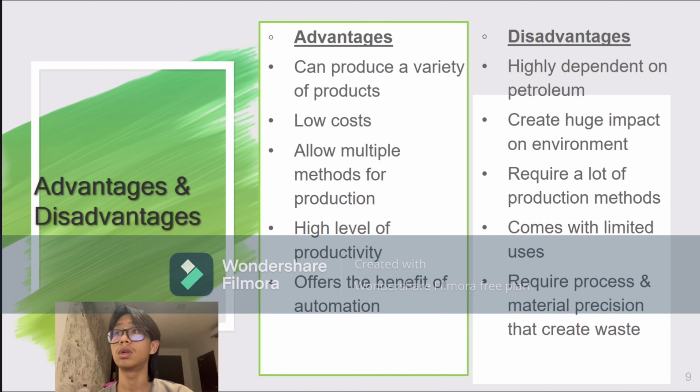The second one is it comes with low cost. With a focus on extrusion blow molding, it uses a lower level of pressure, which means that machinery costs are low, making it easier and more cost efficient to mold external thread or open-ended and large parts, which can be split by opening a closed mold. Moreover, the use of this technology will allow you to reduce labor costs.